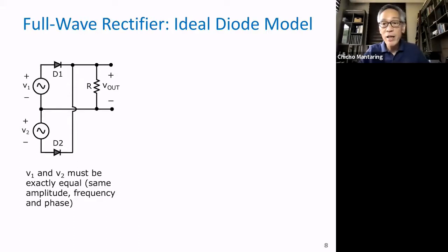In the half wave rectifier, we saw, and this was well pointed out by one of your classmates, that during the negative half cycle, the source does not supply energy. What we want is for the source to supply energy both during the positive half cycle and the negative half cycle, while still performing the function of rectification. That is, while still converting from AC to DC.